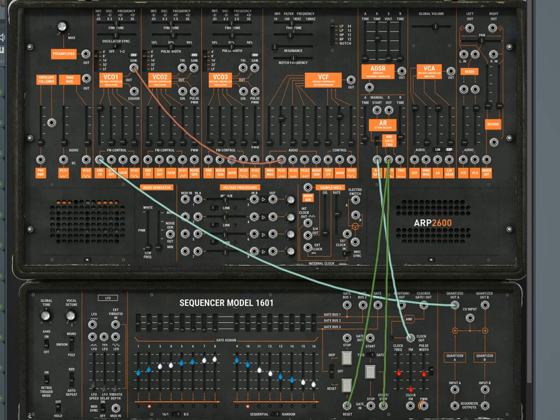The sequencer can be used to control something besides the pitch. Let's disconnect this. Now we're back to keyboard control. Although the clock is still controlling the firing of the envelope. Now let's use the sequencer to control the frequency of the filter. We'll put it into this control of the filter, which was previously the ADSR envelope. Now the pitch won't change, but the sequencer will be controlling the cutoff frequency of the filter. I'll adjust the frequency.